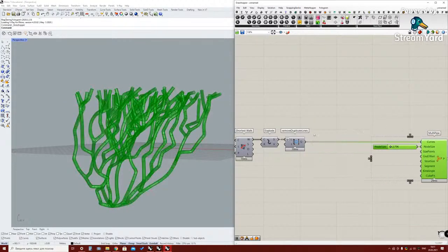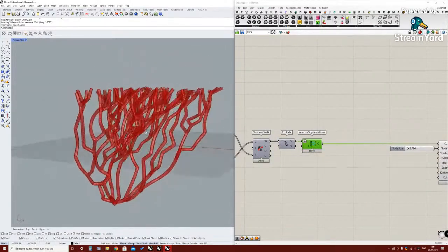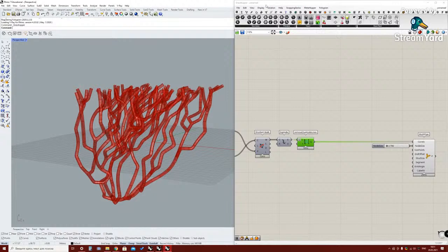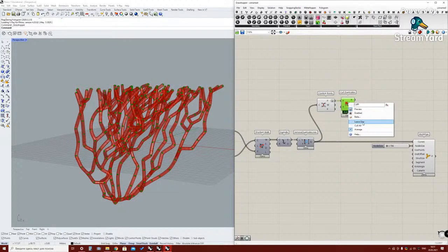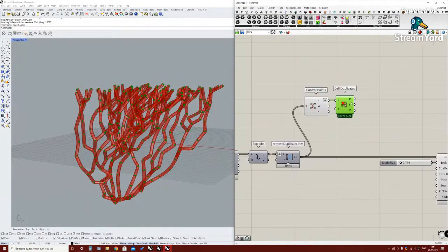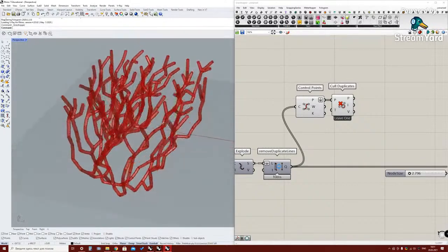And we're going to do it using points from our curves. Let's find all the control points. For curves, I will flatten the list and I will remove duplicates using the cull duplicate points component. I will leave one point in place. Let's see. Okay, yeah, twice less. Perfect.